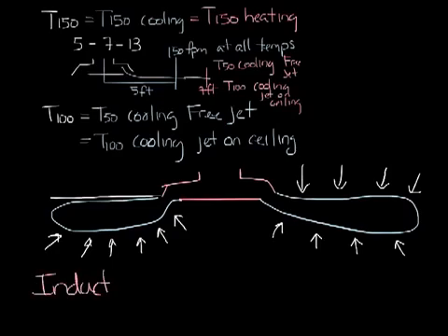Induction is when room air is mixed into the supply air stream. Induction of room air slows the jet down and shortens its throw.